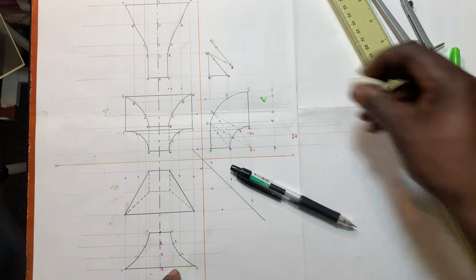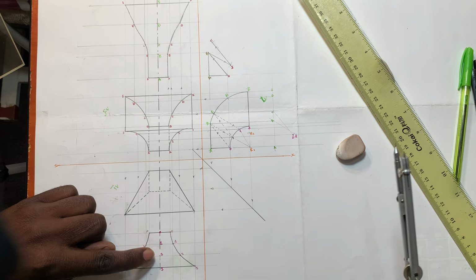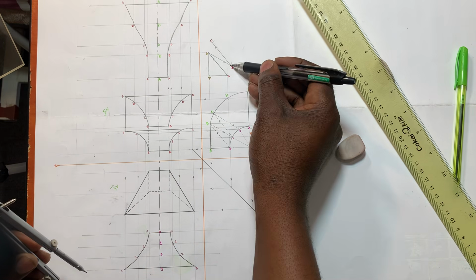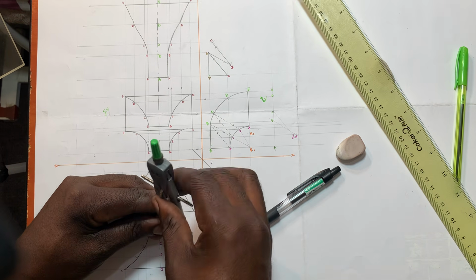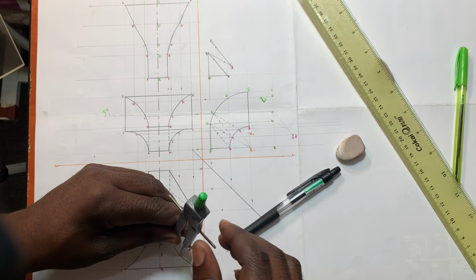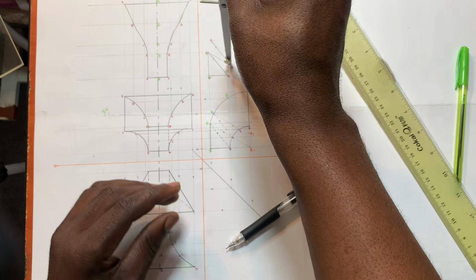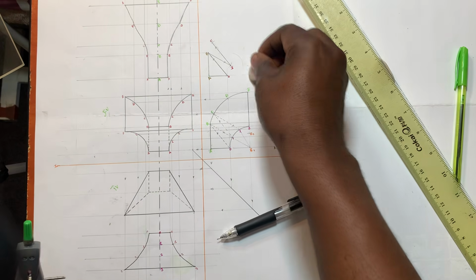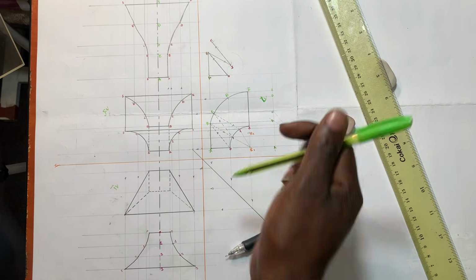Remember, I have to strike an arc of 2. Understand? So you come to a development of the bottom part. You place it at what? At 1, since you have 0, 1. Place it at 1. Further extend it to 2, which is this one. So there it goes. Once it touches there, you come to a development, place it here, then you strike this arc. So there it goes. So within this arc, we have to get point what? Point 2. So which is C to 2.